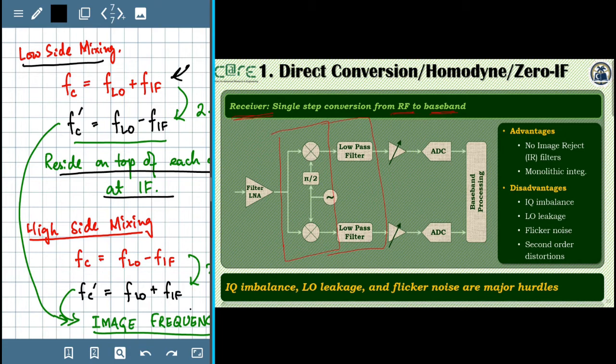There is an issue of IQ imbalance. So if there is any imbalance in phase or in frequency or in amplitude, that leads to distortions. And why is that the case? The problem here is that the IQ mixer needs to operate at a range of carrier frequencies. So depending upon whatever is currently the active carrier frequency, it needs to be tuned to that particular carrier frequency, and it's difficult to maintain the phase and amplitude balance for a wide range of carrier frequencies.